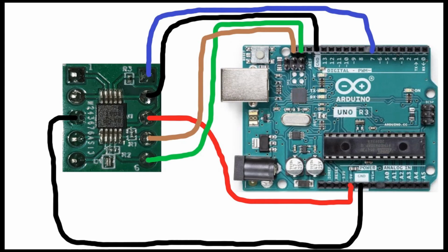Now, it's always recommended to ground the pin if you are going to use the default value. Even though the ADS will use it by default, it's best not to leave the pin floating, because anything can cause the address to change while it's floating, and you do not want the address changing in your programming. So if you are going to use a default value, be sure that you ground the pin.